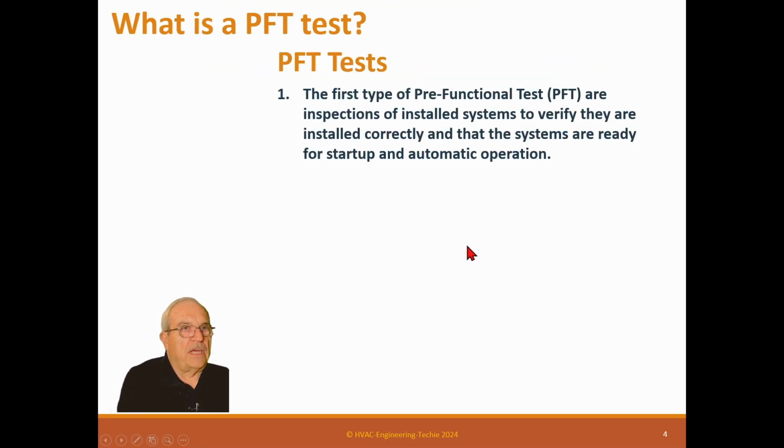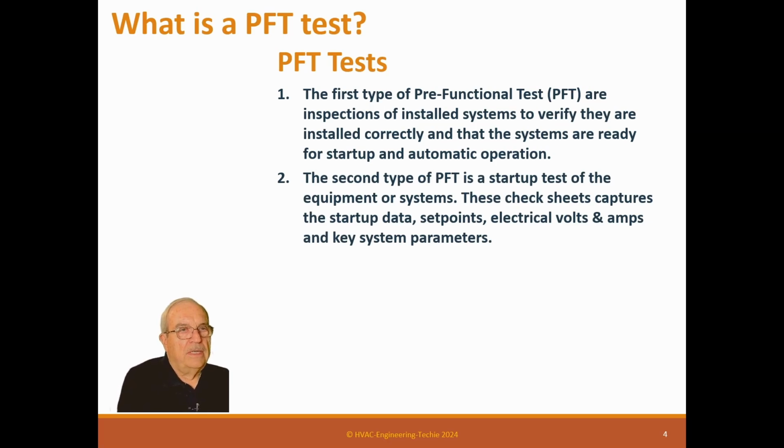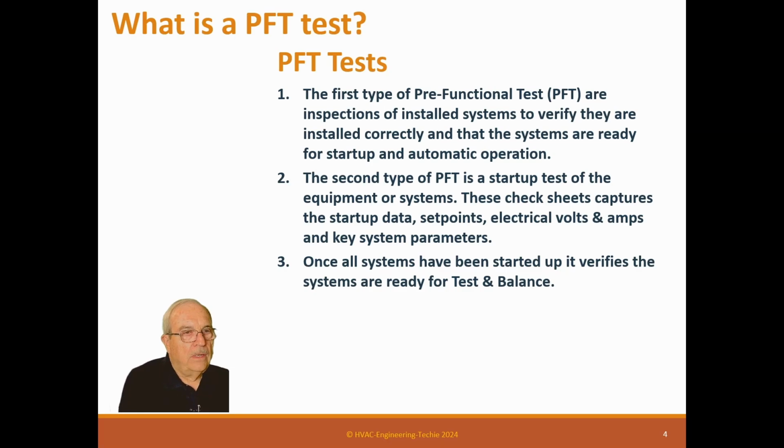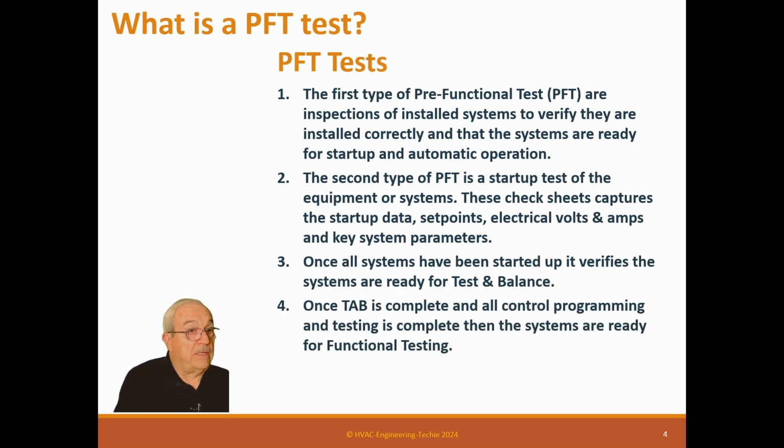PFT tests. The first type of pre-functional tests are inspections of installed systems to verify they are installed correctly and that the systems are ready for startup and automatic operations. The second type of PFT test is a startup test of the equipment or systems. These check sheets capture the startup data, set points, electric volts and amps, and key system parameters. Once all systems have been started up, it verifies the systems are ready to be tested and balanced. Once TAB is complete and all control programming and testing is complete, then the systems are ready for functional testing.